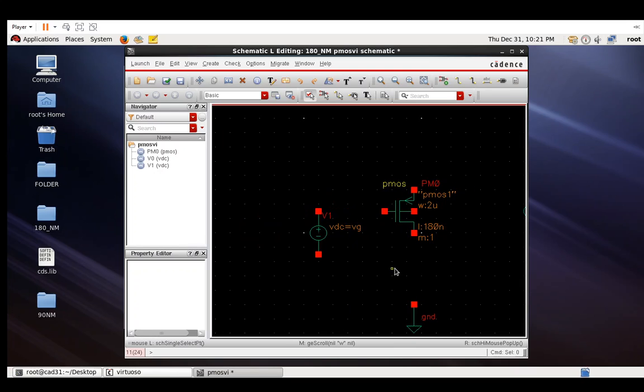So we have to remember a few things. Okay, so this is a transistor, pMOS transistor. If you click on this terminal, okay, it becomes pink color. It's called G, that is for gate. Okay, the top is source and the bottom is drain, and this is fixed in this simulator. Even though theoretically source and drain are interchangeable in most circuits, even in practical circuits, okay, one will always be acting as source and one will always be acting as drain. And in the simulator also, for the sake of naming, because the simulator cannot automatically decide, they have fixed this terminal with the arrow mark as always the source terminal.